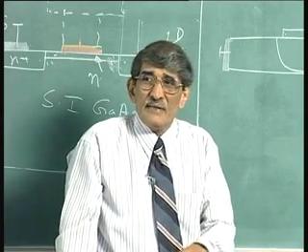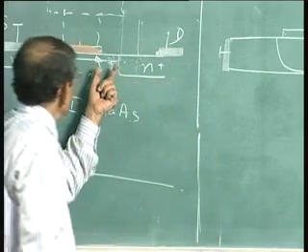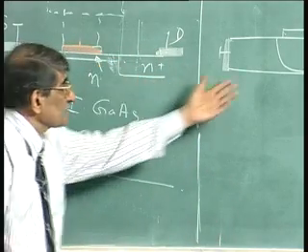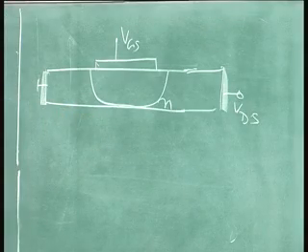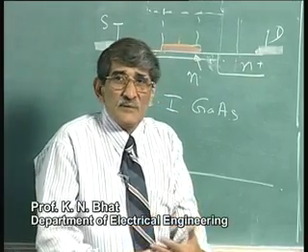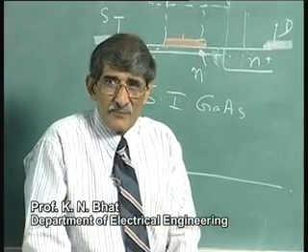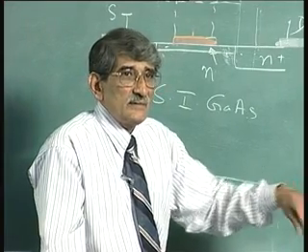That effect should have been the same whether it is 0.15 micron or 0.3 micron, that curvature effect. But something more happens. The way you measure the threshold voltage, in fact, you are seeing the threshold voltage with the VDS applied. That is what is important for you. When you apply VDS, when can you shut off this device?